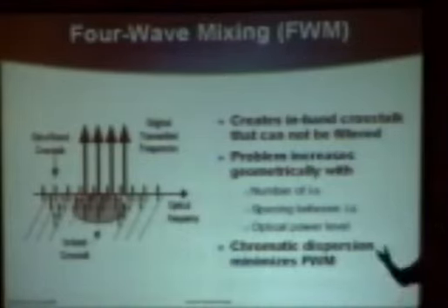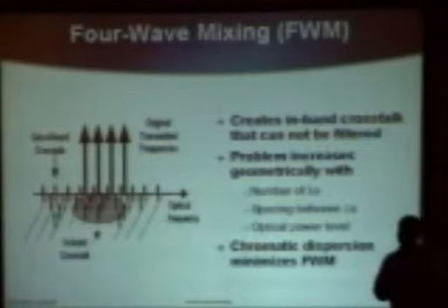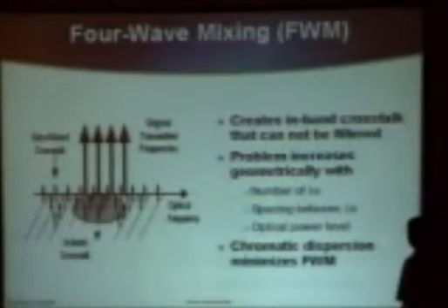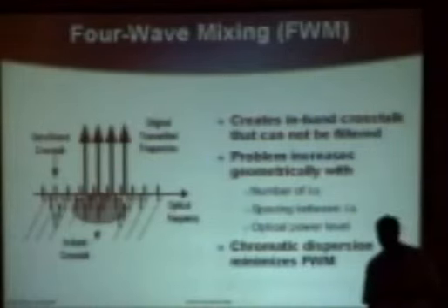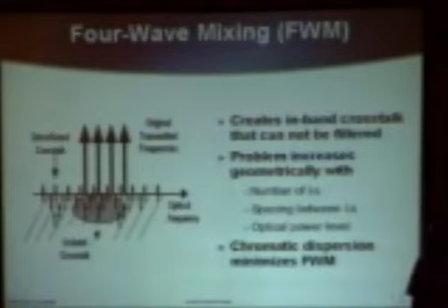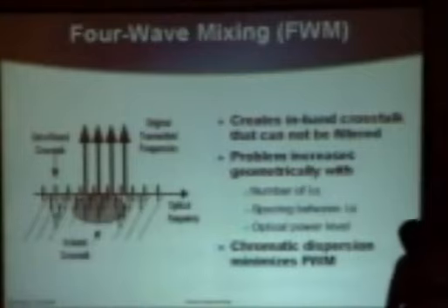If we increase the bit rate, we have more problems with chromatic dispersion. If we lower our dispersion on the fiber to correct for that problem, we cause four-wave mixing problems, and it's a careful balancing act going back and forth between these three simple nonlinearities and a whole host of others that are carefully balanced at the analog transmission level to make it all work.